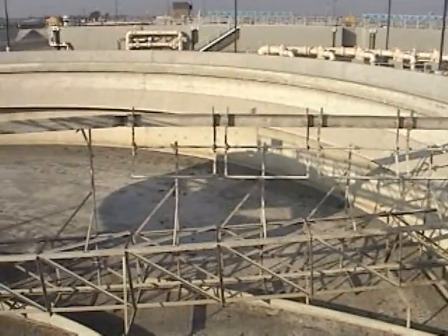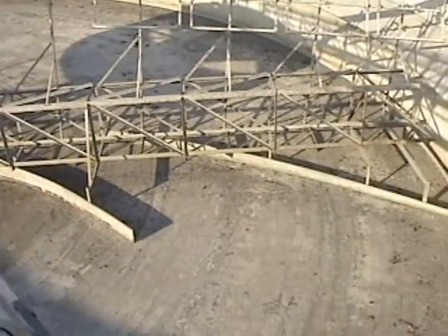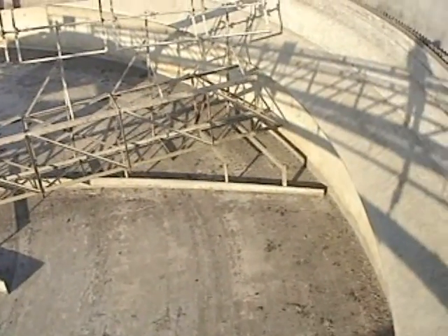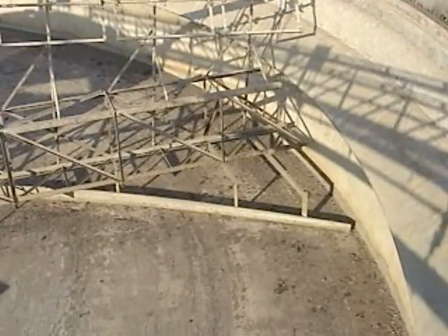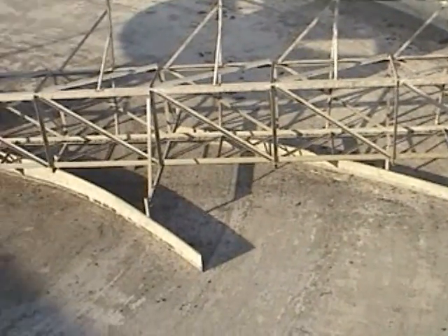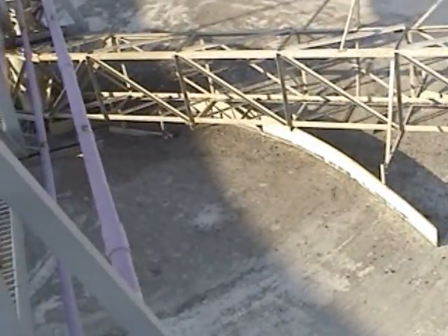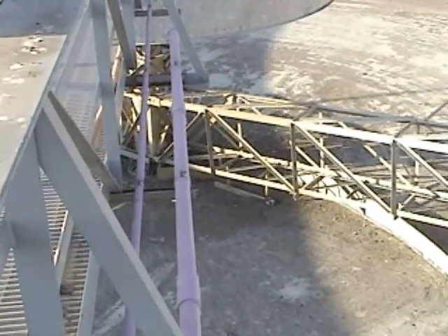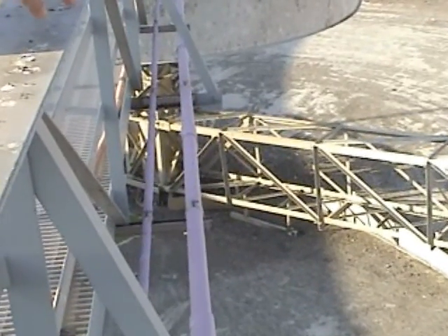They're hinged so that as it pushes the scum along, it'll hit the ducking skimmer right here beneath me, and this will rotate down after the flights hit the whisker switch over there. The sweep right there will push the scum into the skimmer right here, and then they'll rotate down and flow beneath the skimmer. So that's how we're able to skim the solids off the secondary clarifier. On the bottom, you can see the scrapers, and what they're doing is pushing the settling mixed liquor, well, now it's return activated sludge, to the center of the clarifier, to that trough down there where the RAS pumps can pick it up and send it back into the aeration basins.